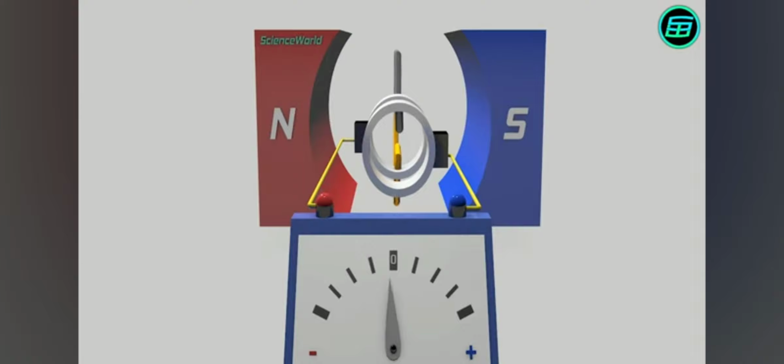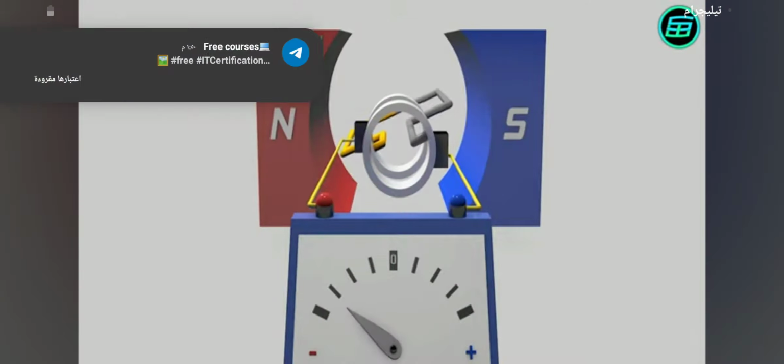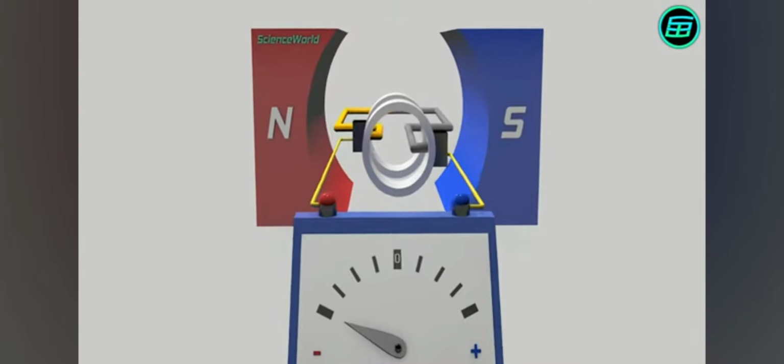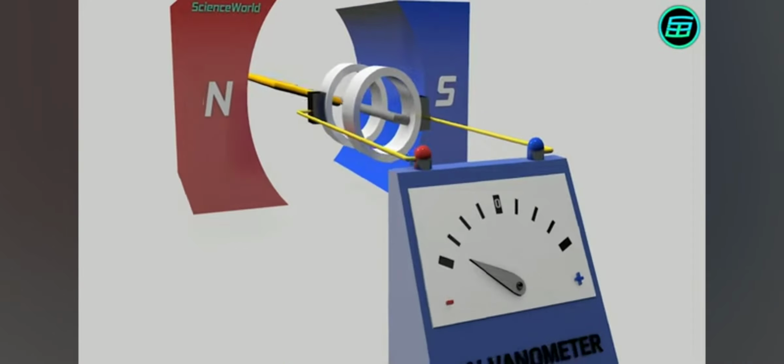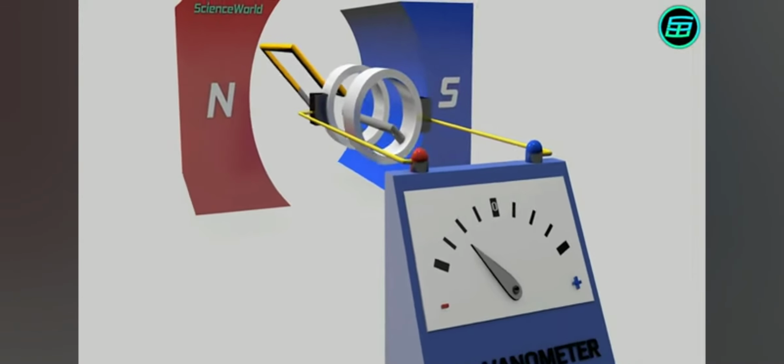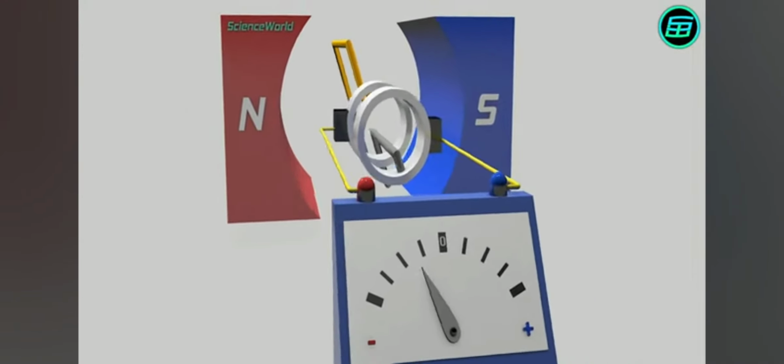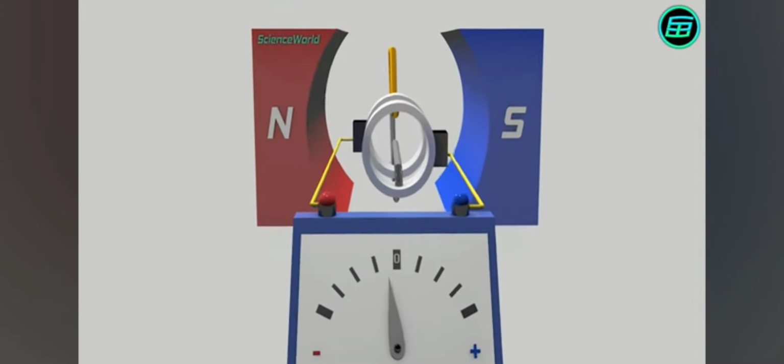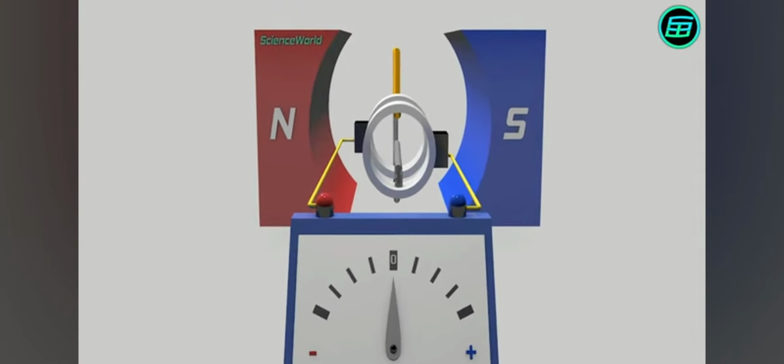As the armature keeps rotating, the magnetic flux starts to change again and reaches its maximum when the yellow armature part approaches the magnet. As the armature rotates further, the change of the magnetic flux decreases until it becomes zero and the cycle is completed. Between half and complete cycle, Fleming's right-hand rule indicates that the direction of current is outward.